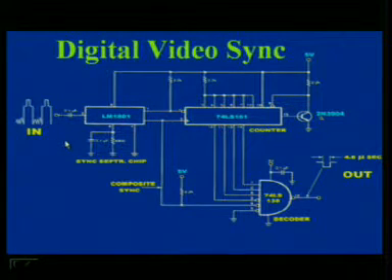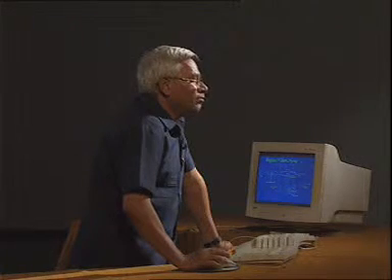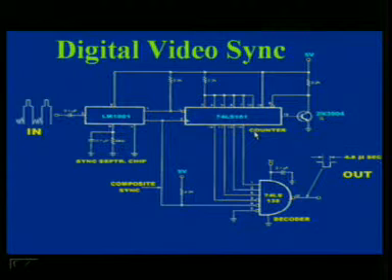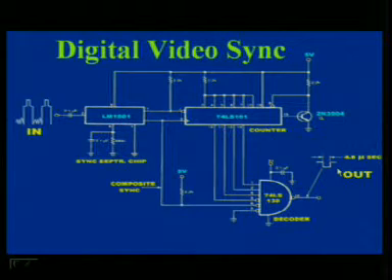Sync separation as a video level is same, but the timings are different. Through the counters, this counter maintains the exact timing of sync pulses. I mean to say, if the frequency of either horizontal or vertical oscillator or even phase changes, the position of sync pulses will differ and we may not get the sync pulses. Therefore, in case of the digital video, exact timings are needed.